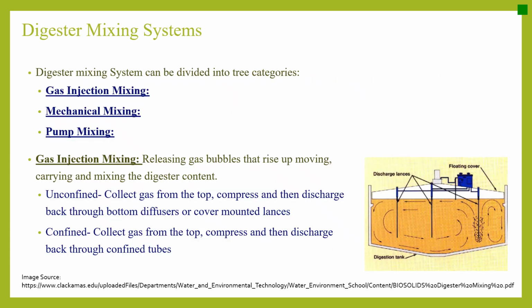Let's move to digester mixing systems. Digester mixing systems can be three different types: gas injection mixing, mechanical mixing, and pump mixing. Gas injection mixing is done by releasing gas bubbles that rise up, moving, carrying, and mixing the digester content.